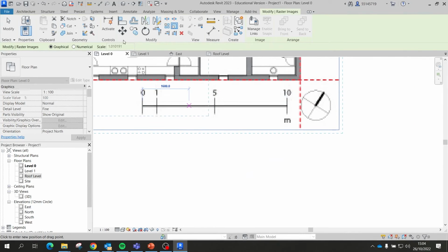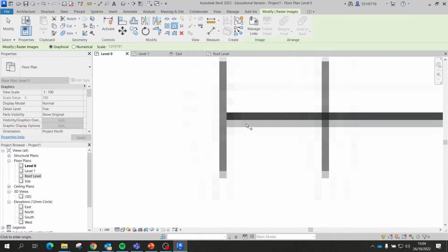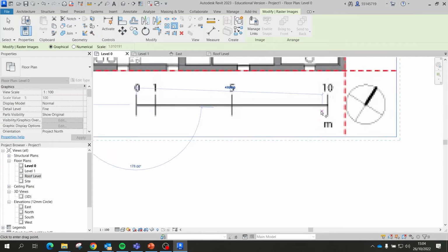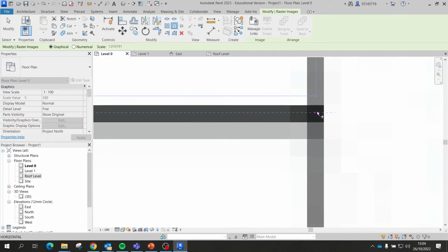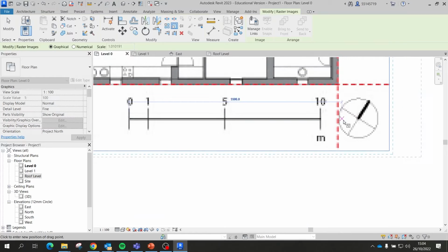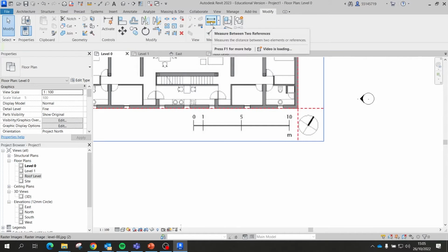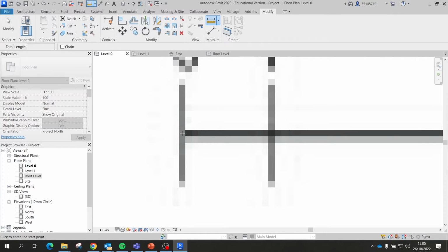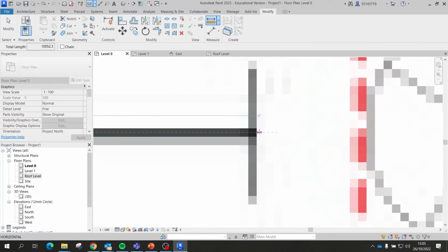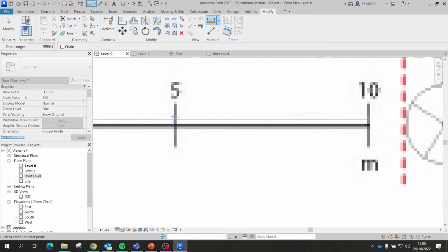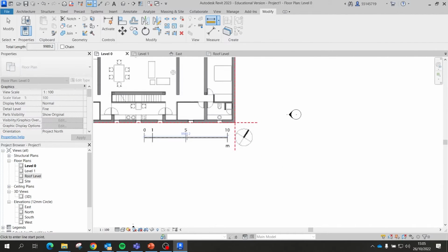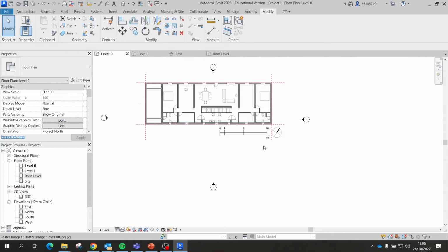And then instead of being graphical, I can change this to numerical. Oh, sorry, no, actually, I'm gonna keep it graphical, because I don't know exactly how much I need to scale. Go in here, and I simply start typing 10,000. And then now, if I check the measure between these 2 points, that should be 10,000, so 10 meters. Well, roughly, right? It's 9999.2. Yeah, it depends where you get the point. So 10,000, perfect.